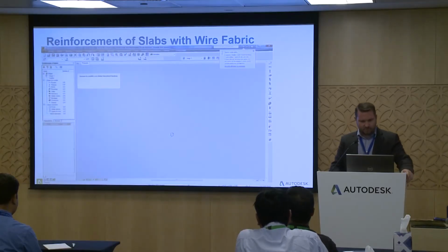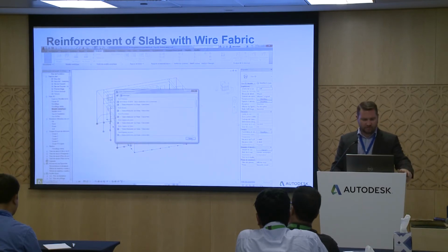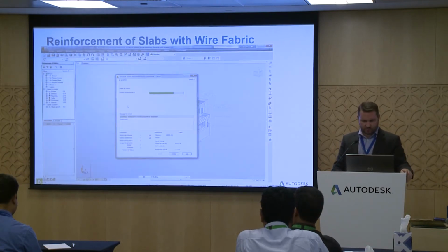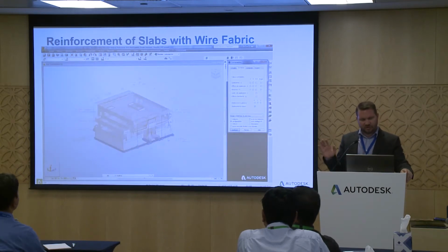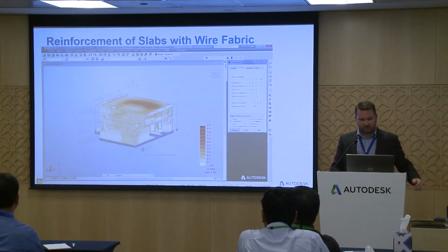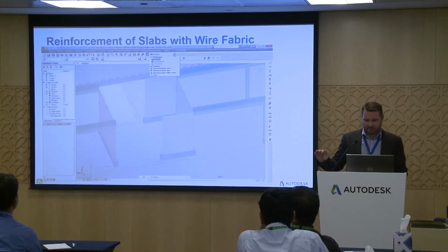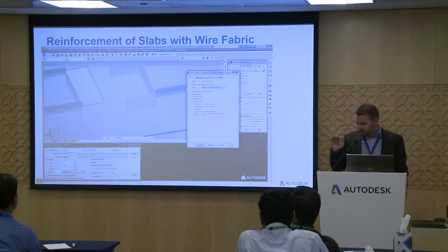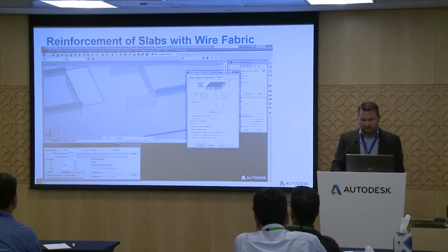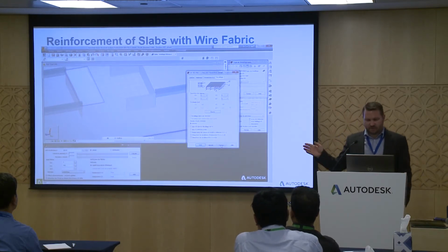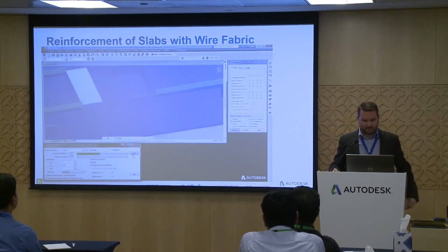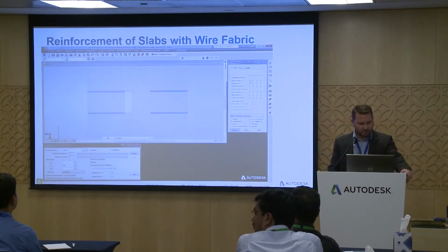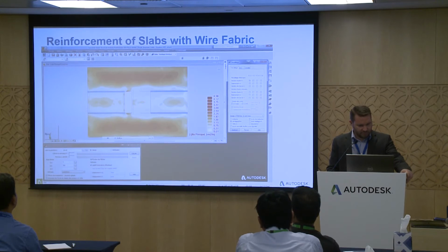So here I proceed the same. After I change my mind, so I take only a small Robot file only with the slab here. You see there is only the slab and the support of the slab. It's because it gives a better result for what I need, in fact, because I don't have all the rigidity of all stairs. So here I do the Eurocode 2 post-treatment. So I have the needed reinforcement.